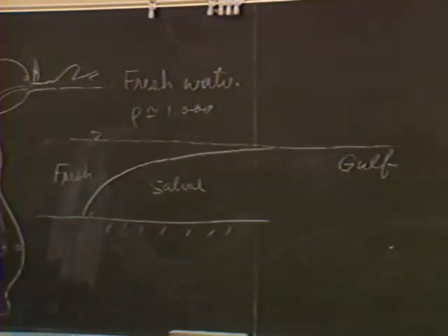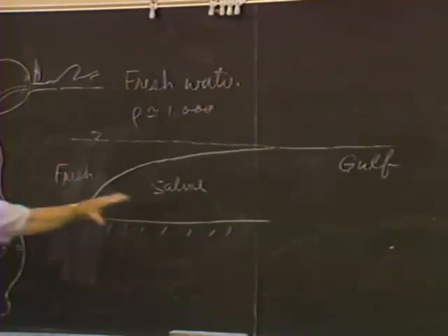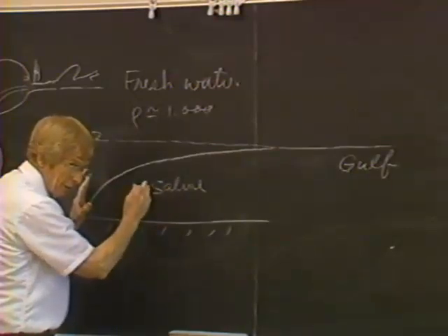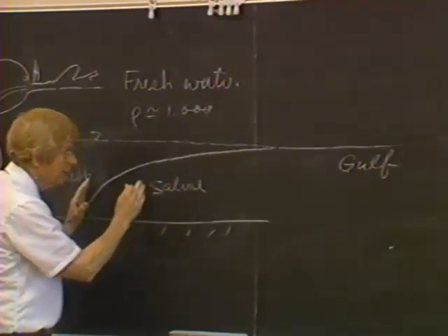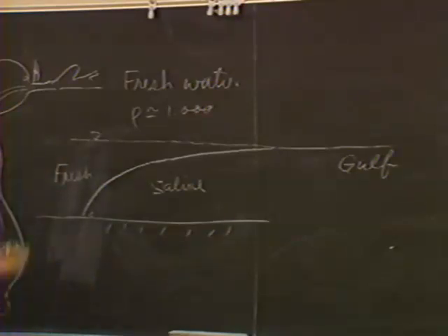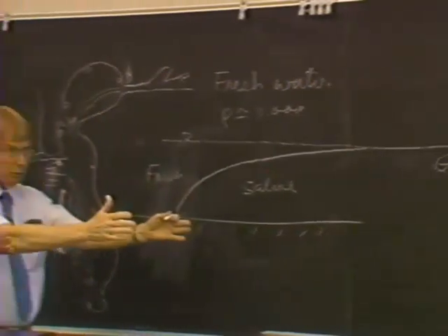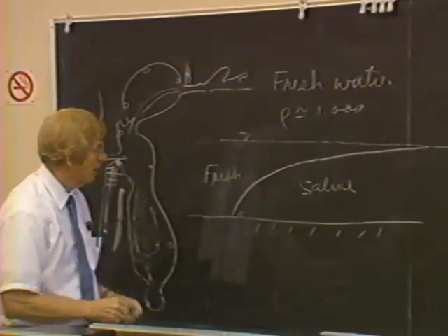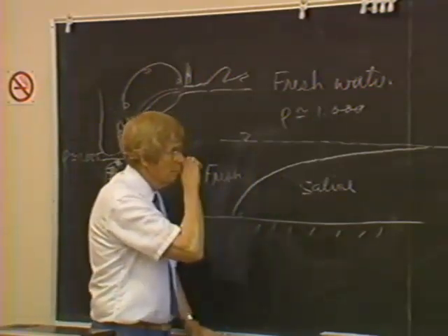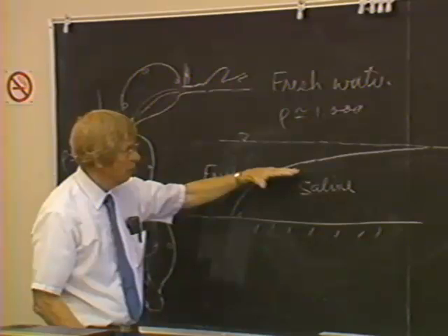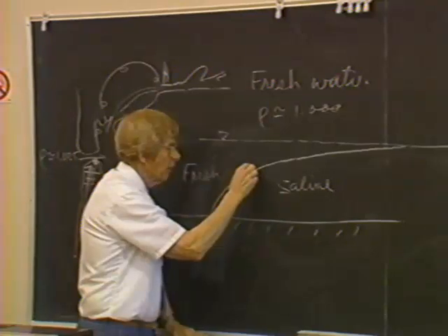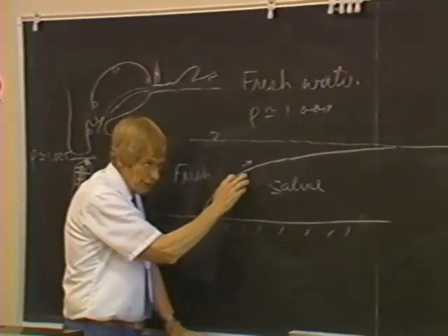It's very pronounced in the Mississippi, and the reason is that there's a high freshwater flow and there's very little tide out here, so there's very little movement back and forth in the inlet. I should point out that the mouth of the Mississippi is a stream through a delta, so it doesn't change in width much with distance. In any case, there's a very sharp front here. These fronts are observed where there's little back and forth motion, and where the velocity of flow along here is not one that generates waves.